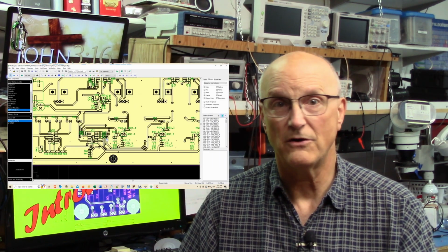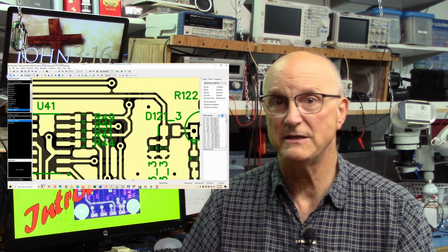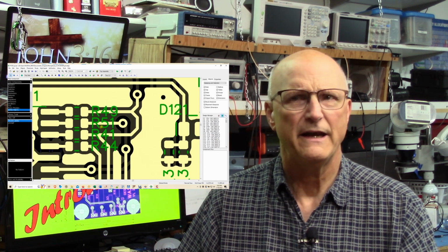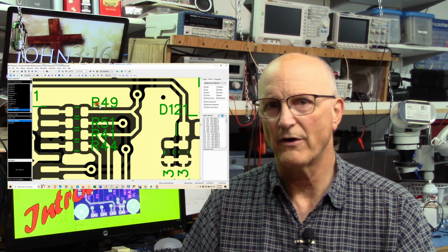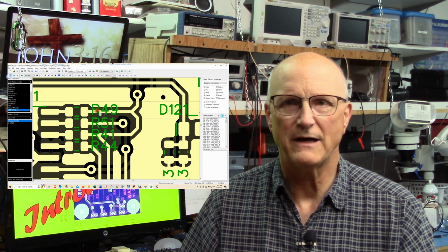This text is all traditionally created in the PCB design software, and it is used to create a silkscreen which they lay over the board, then squeegee white epoxy ink onto. The ink passes through the silkscreen in the open spots, placing the text on the board. Because of the process used, this white text we see is called the silkscreen layer. Like the solder mask, it only resides on the outside of the board.